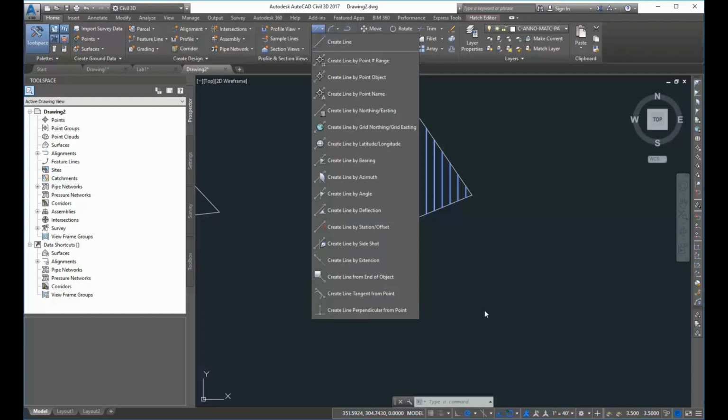Recognize that with a blank drawing, you're going to be nowhere near where those coordinates are. So the first thing you do is put in that northing and easting, and you want to create a line that's about 100 feet north and 100 feet east. All you're doing is adding 100 to that north coordinate and that east coordinate, and you'll get a line in there.